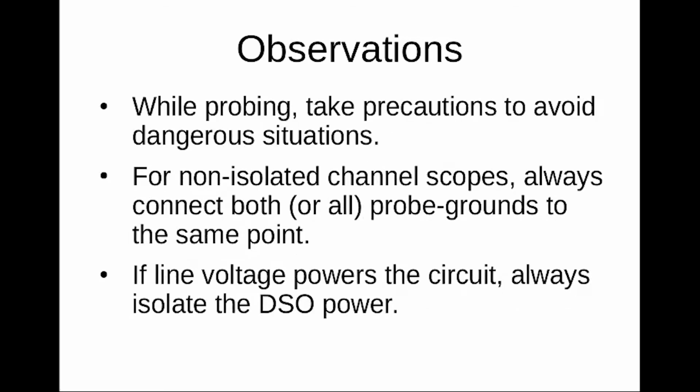Now, while probing, take precautions to avoid dangerous situations. For non-isolated channel scopes, always connect both or all the probe grounds to the same point. If the line voltage powers the circuit, then always isolate the DSO power or isolate your circuit using an isolation transformer. Now why this is required is because just as I mentioned the case of gate drive circuit and why isolation is required in such a circuit,